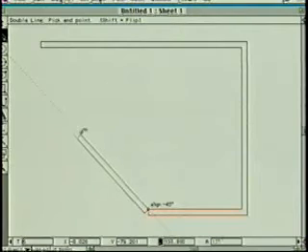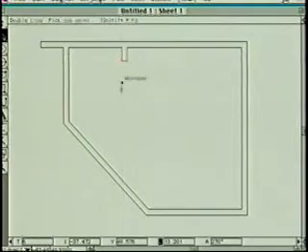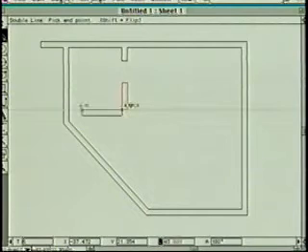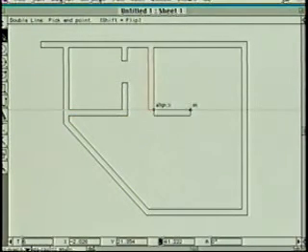If I do a 45-degree miter, that will clean up. If I come into a T, that cleans up. These Smart Walls are very nice, so then I can just quickly latch in a part, skip for a doorway, come across. And because of the automatic aligning of the Drafting Assistant and the intelligence of the Smart Wall, I can just very quickly go in and lay out. I can hold the Shift key, flip that to the other side, and just get a very quick layout.